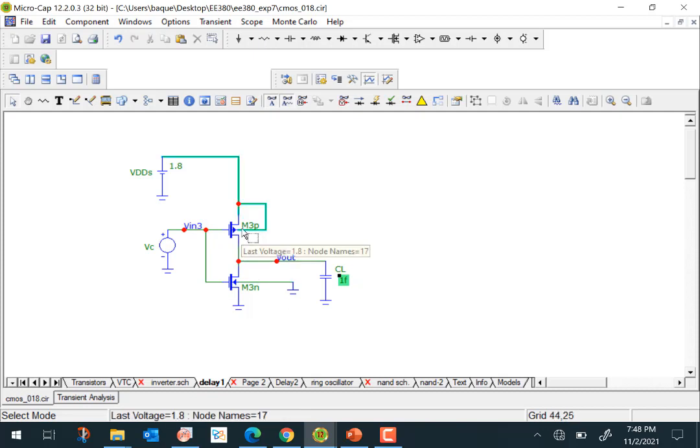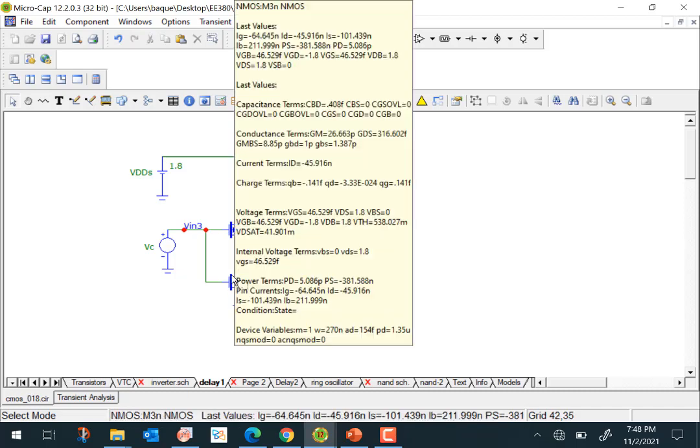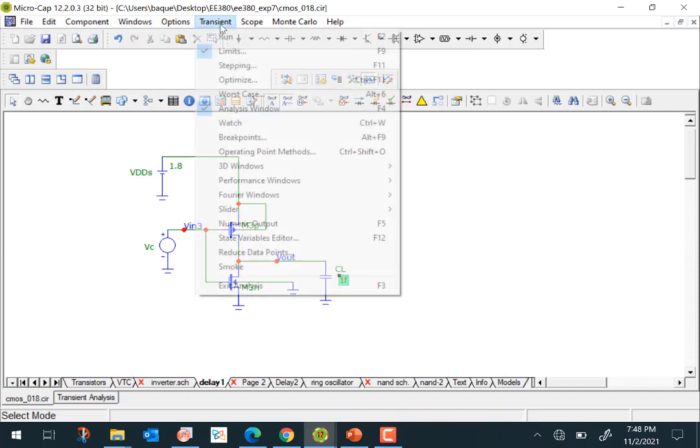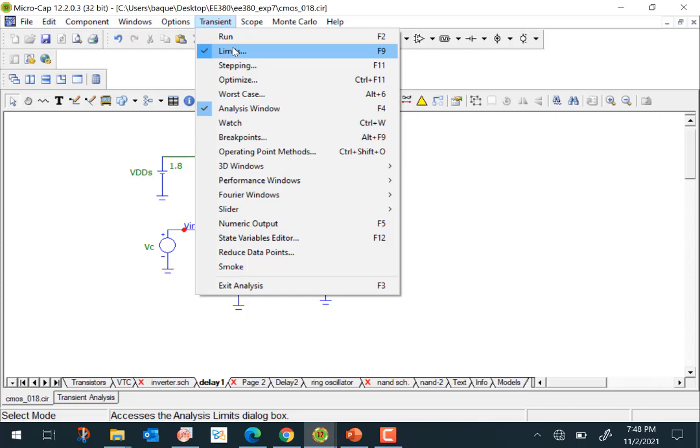In a CMOS case, the primary power dissipation is what we call the dynamic power dissipation. That comes about because of the charging. Whenever the capacitor has to be charged, the current has to flow through the PMOS, let's say, and it has a resistance, so power is dissipated. Similarly, when the capacitor is discharged, current flows through this NMOS and through a resistor, so power is dissipated. So you can also study the power dissipation part.